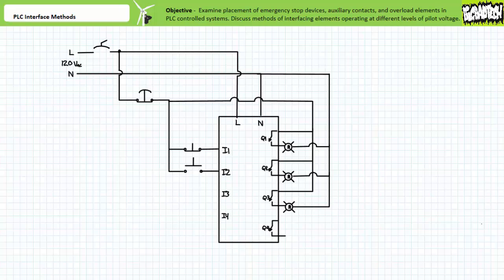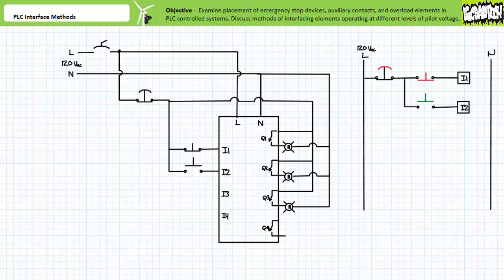Consider our present configuration illustrated far more efficiently in the following fashion. Here, the hardwired connection between the e-stop and the two downstream field input devices, the normally closed momentary contact red push button and the normally open momentary contact green push button, is made pretty explicit. However, the field signals kind of disappear down the rabbit hole of the appropriate PLC inputs. This is to imply an isolation between the field inputs and the PLC exists, and the PLC program assumes responsibility for all incoming transmissions from this point on.